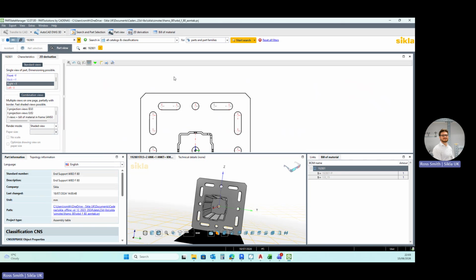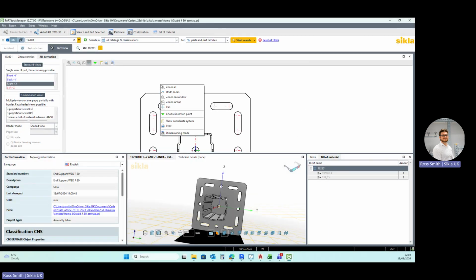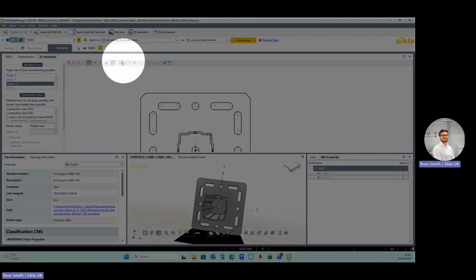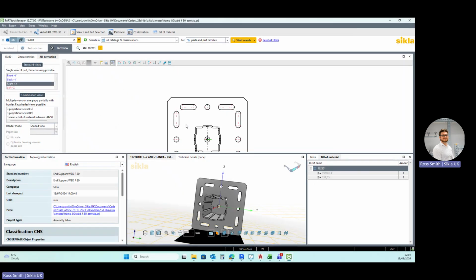And what we do here is to get the measurement tool live up above, I can right click and enter dimensioning mode, and you can see extra tools appear within this ribbon bar. So let's say I wanted to know the distance between here and here. We can do a horizontal measurement. And you can see, before I left click, there are certain snap points within this item.